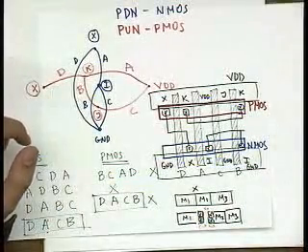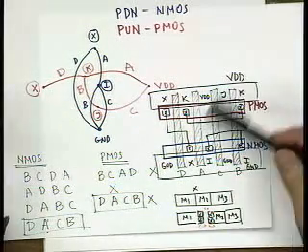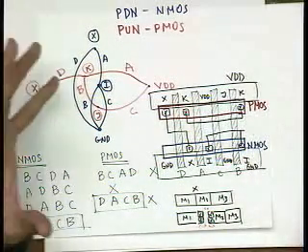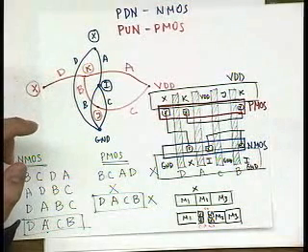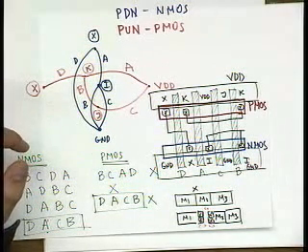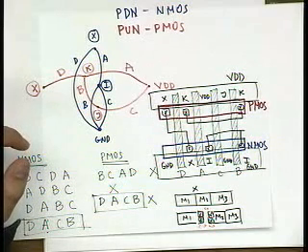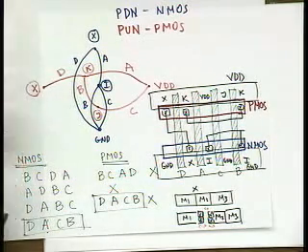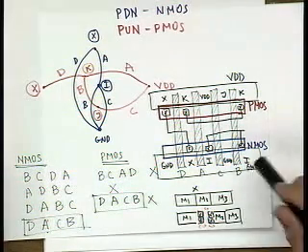In practice, it is getting more complicated, but basically this is the principle that you use to have all these diffusions uninterrupted, and I will come back to different W in a second. I have illustrations for that, for the layout. But you are correct. We will come to that in a second for the propagation delay analysis when we have to consider different sizing. How do we size all these things such that we have the same pull up, pull down, and things in general? Yes, you have different Ws, but this is the principle.